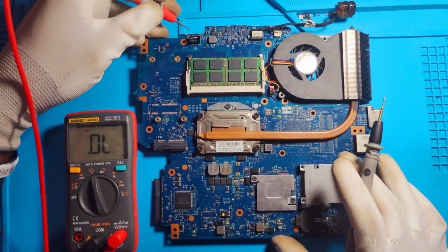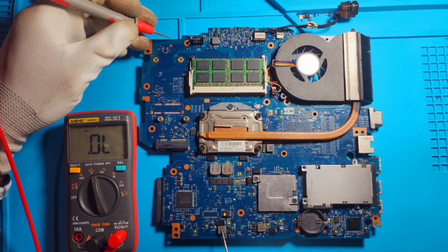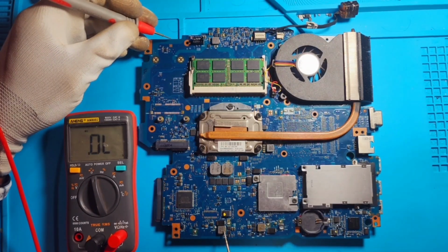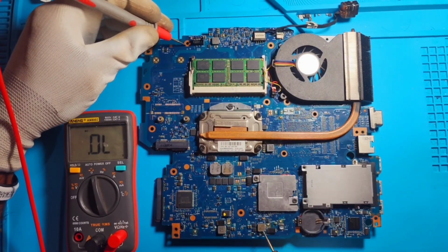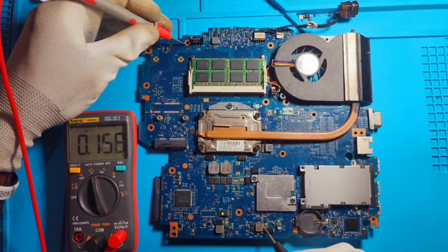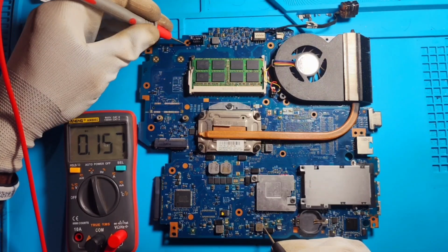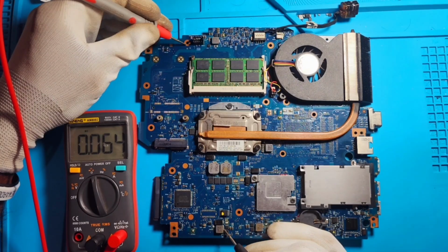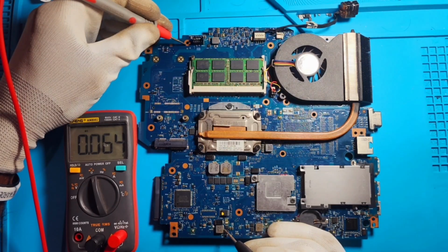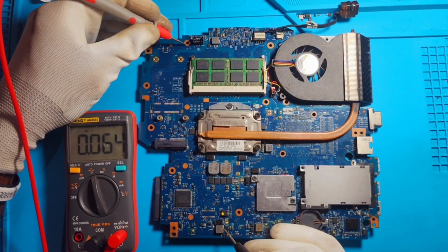But when you look at here, this is the 5-volt coil of this motherboard, and this is the 3-volt coil of this motherboard. When you check the diode value at this point here, it is showing 157, that is okay. But at this point, it is showing 64. So this is a bit lesser than normal. But anyway, let us keep it as it is. Let us check and come back.